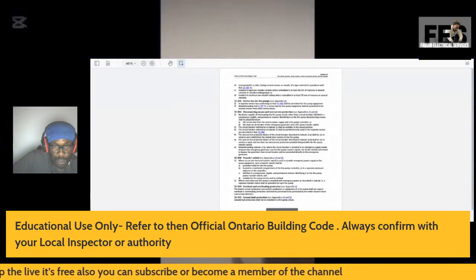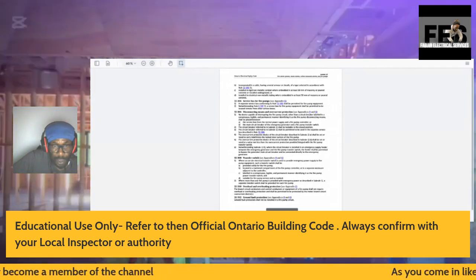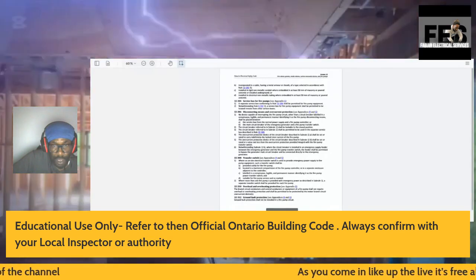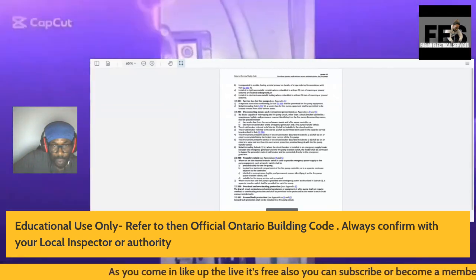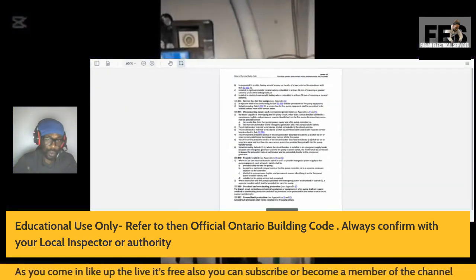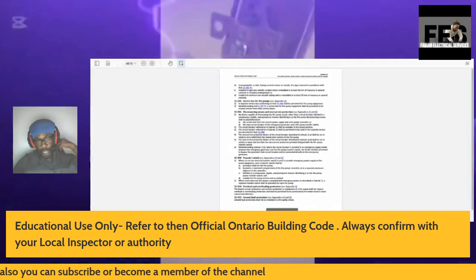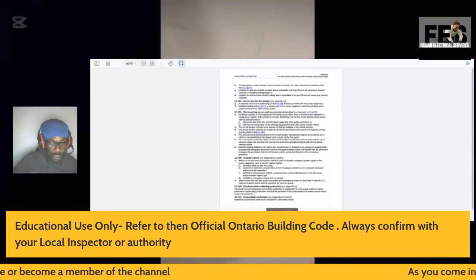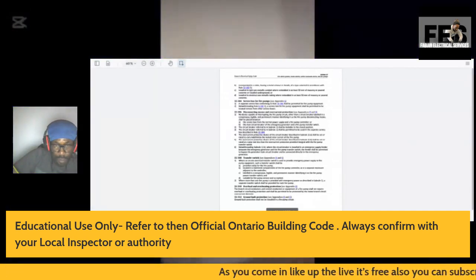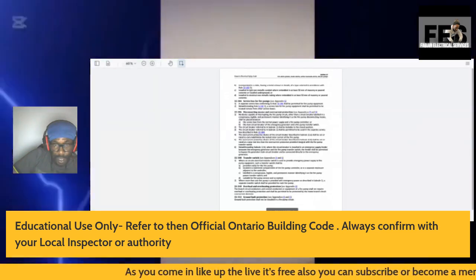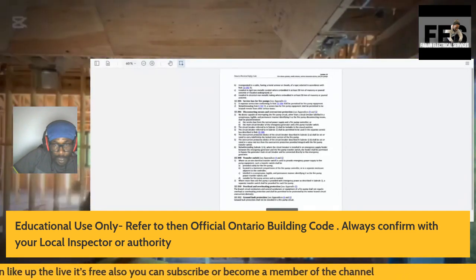The circuit breaker referred to in Subrule 1 shall be lockable in the closed position. The circuit breaker referred to in Subrule 1 shall be permitted to be used in a separate service box described in Rule 32-304. So it's giving you the rule you can do, but it's also telling you to refer to 32-304.